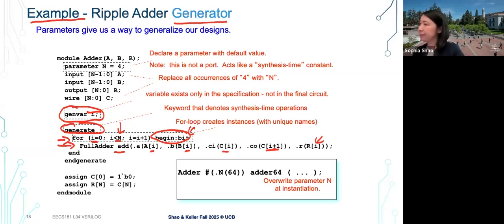The structural syntax is making the gates. You're doing that explicitly, yes. And here you are not making the gates in HDL yet, but when you synthesize it, it will have multiple copies of the gates. Components can be viewed as things that are generated at synthesis time, yes. So yeah, this can be very useful. You can also see parameterization here to have multi-bit components.